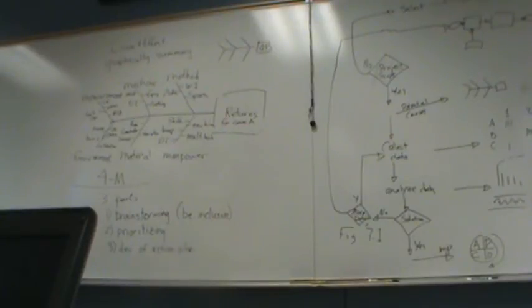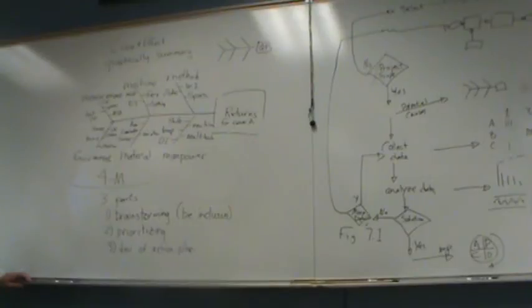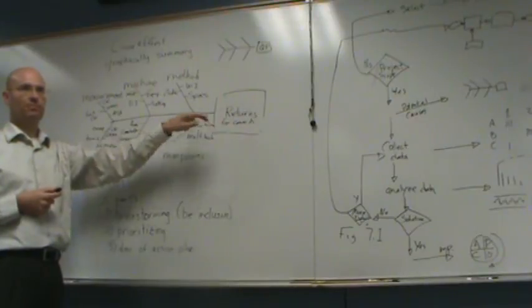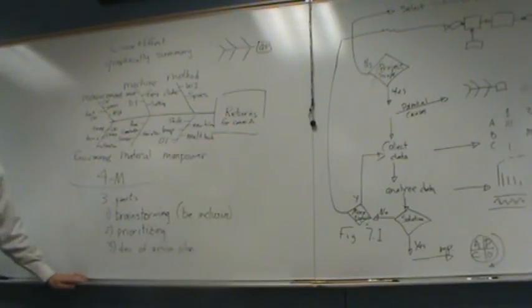And that's why you're getting them on this tree. So before you take them off and decide they're not a root cause, you have to review them. We didn't populate something at a certain reference designator. Starting with method, were the work instructions correct? Were the specifications clear? And so you go through and they come off the list. So you actually use this as a checklist, if you will, to make sure that those possible causes did not cause it.